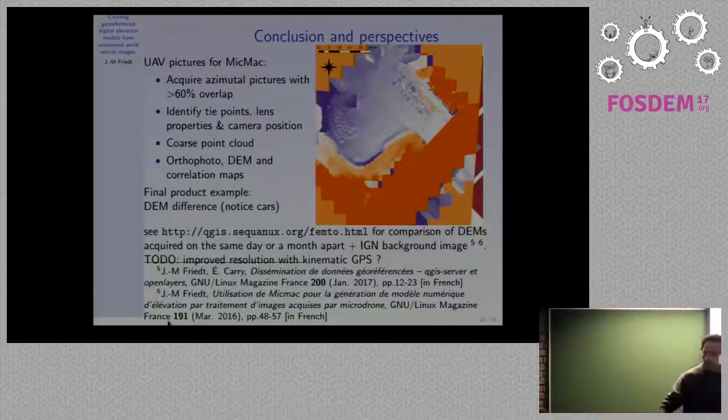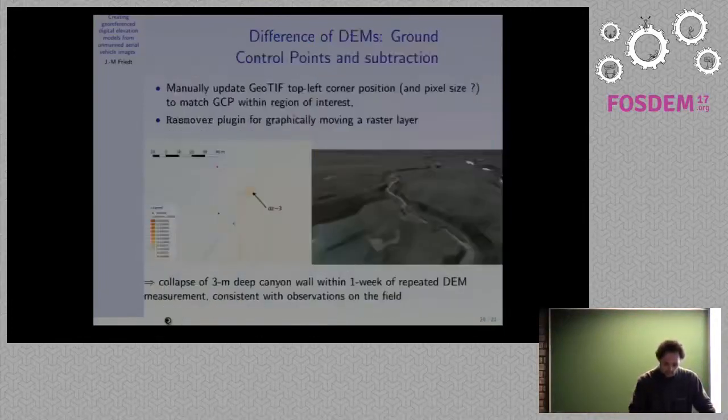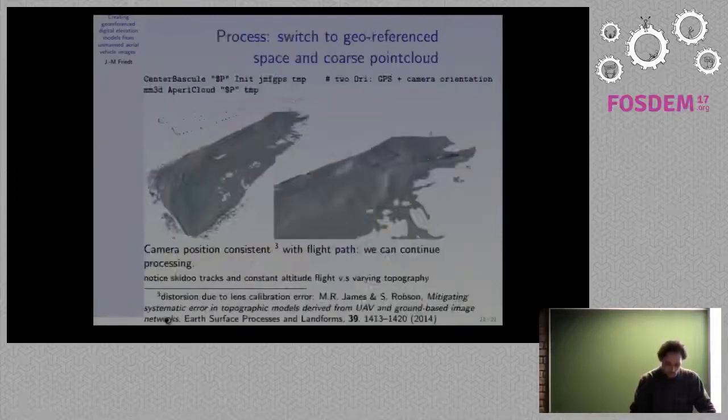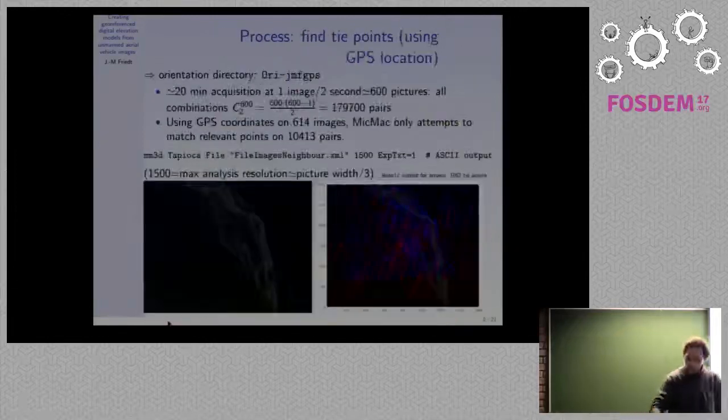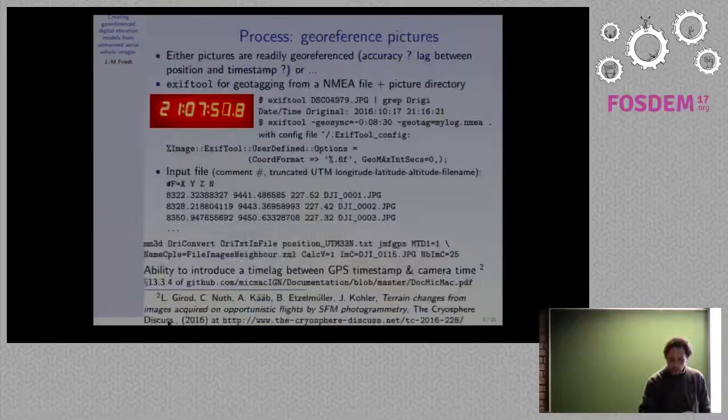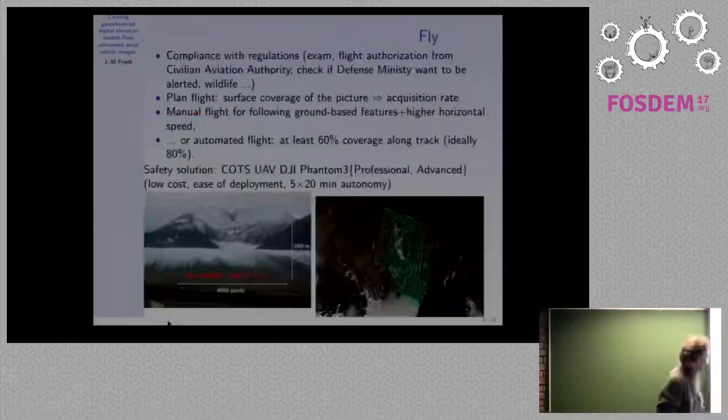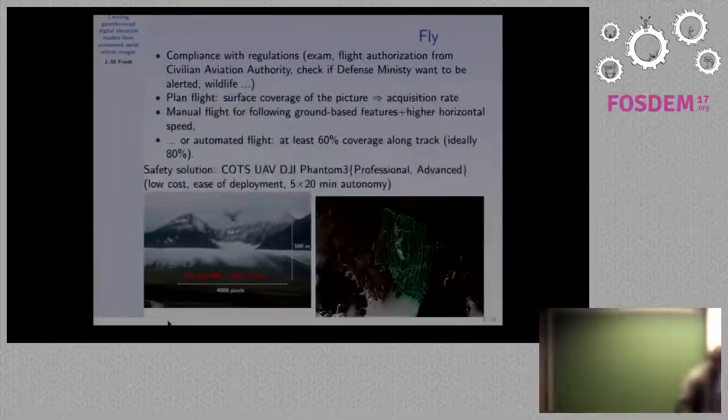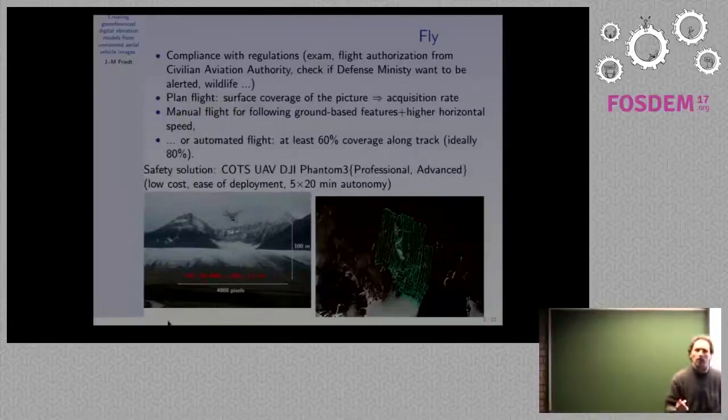Thanks. It's very interesting. I have 2 questions. The altitude is calculated by the angle on which the 2 overlapping pictures differ. So the question is how I select my altitude. Actually, my altitude is a trade-off between the pixel resolution. Here you see that 5 centimeter is actually much below what I expect.